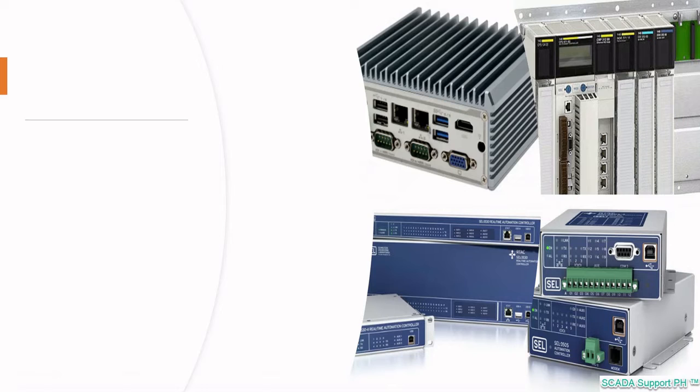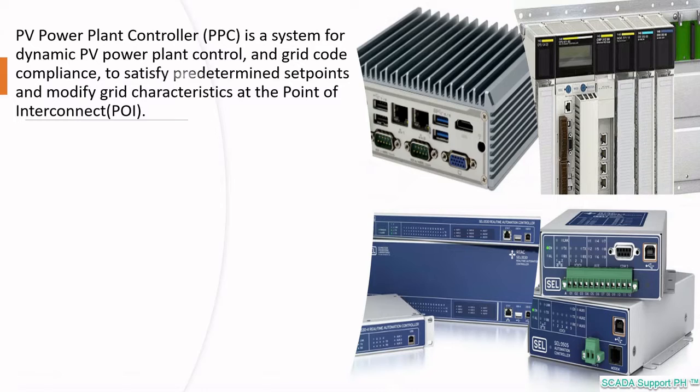Power Plant Controller, or PPC, is an intelligent vendor-independent system for dynamic PV power plant control and grid code compliance. To satisfy predetermined set points and modify grid characteristics at the point of interconnection, or POI, a PPC is utilized to govern and control the network inverters, devices, and equipment at a solar power plant. Site operators can send these set points and parameters directly to the PPC or more frequently via SCADA system.